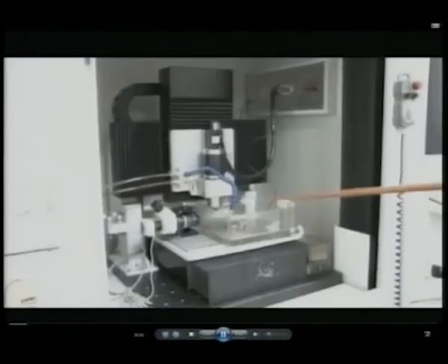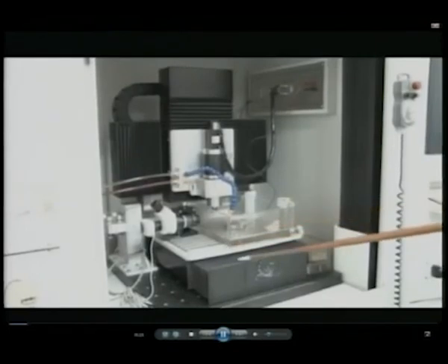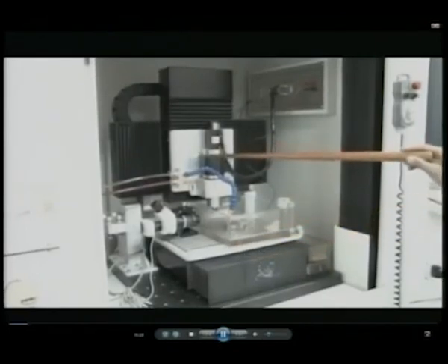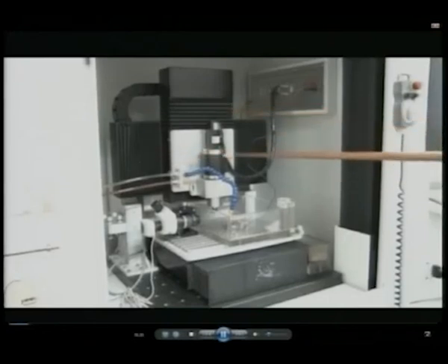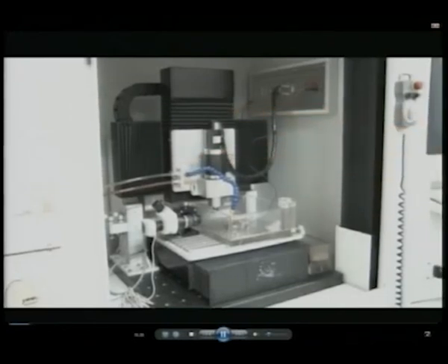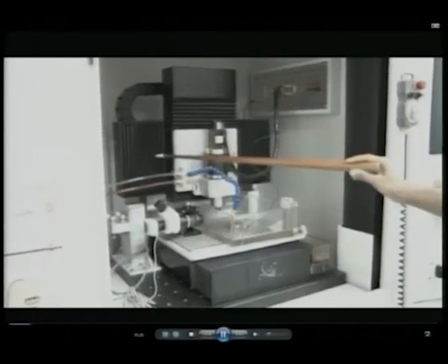In the machine, the horizontal table is controlled by y-axis, whereas the vertical table contains x-axis and z-axis as well as the rotational axis. The axis of travel for each axis is as follows. The x-axis can travel to a maximum distance of 200 mm.